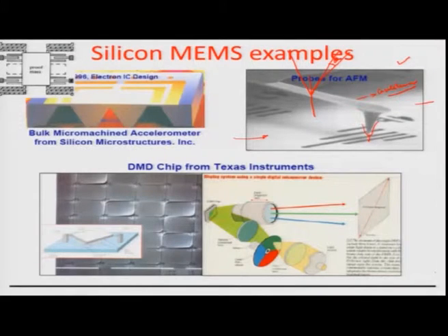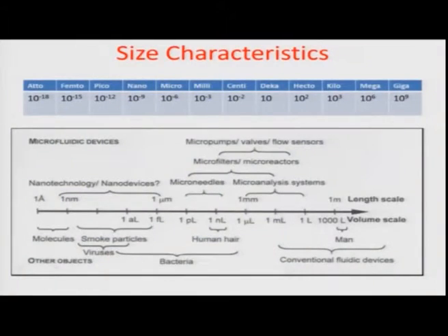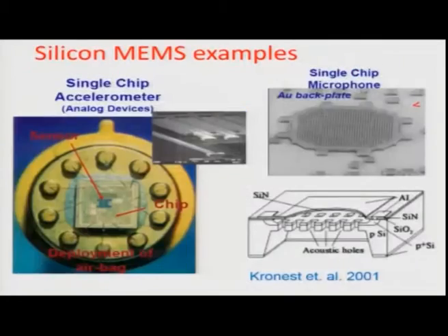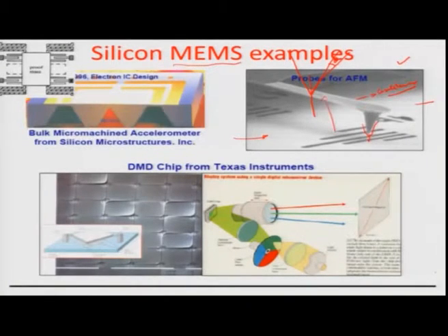It is again a device which comes under the realm of micro electromechanical systems. Think of it as a change in an optical signal because of a bending process which happens right here at this small cantilever tip. So, a mechanical signal is being converted into an optical signal, and then because of that optical signal, an algorithm computes the exact topology over which such a tip scans, which is what is directly visible out of the probe of such an AFM.